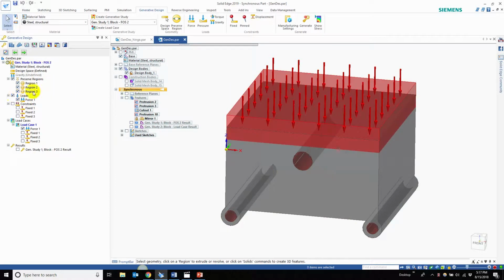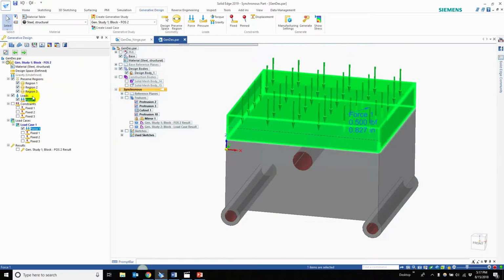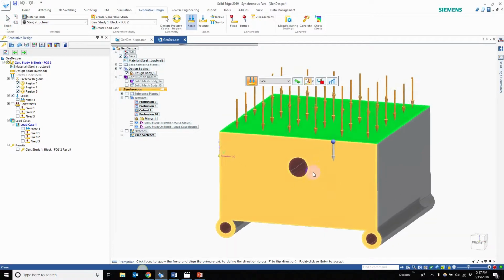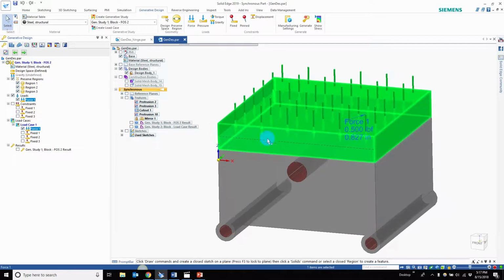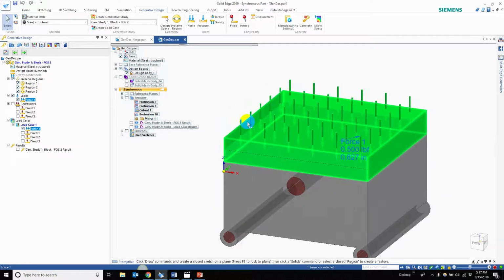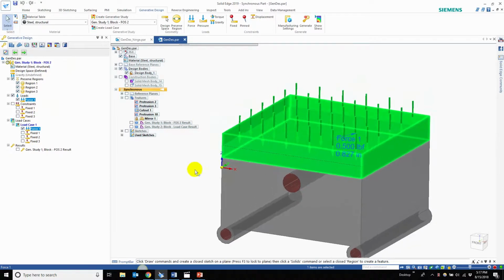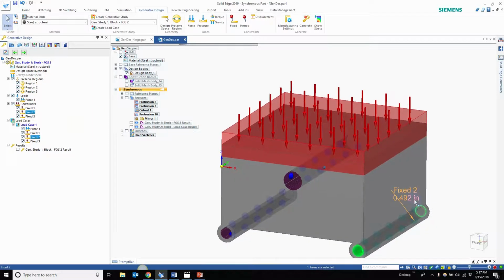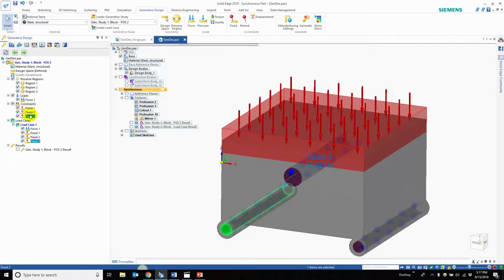The force is going to be a 0.5 pound force load, and 8.827 inches are going to be preserved inside the part. And you could see here in the dotted feature that we're probably going to be expecting a solid rectangular feature once Generative Design has gone through. And we also have fixed constraints with an offset value of 0.827, a fixed constraint of 0.429 and 0.429 as well in the smaller cylindrical features.